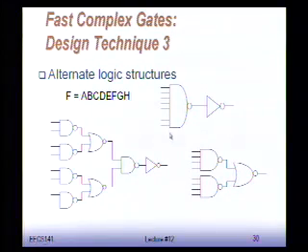But because the delay of this 8-input gate is so big, you're most likely better off by using more stages, each of which has a much smaller delay, than by using a single stage, which has a large delay, okay? And this is just because the number of stages grows slower than the delay if you increase the number of inputs, right? Otherwise, this will not be true.